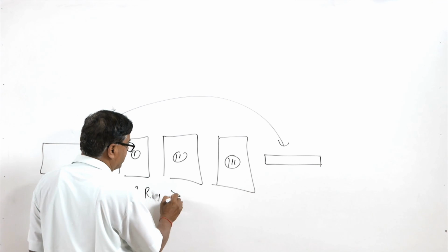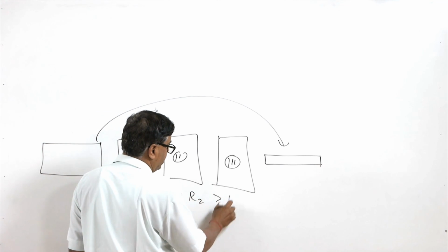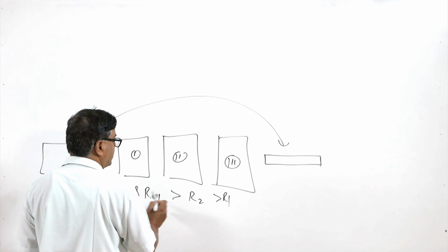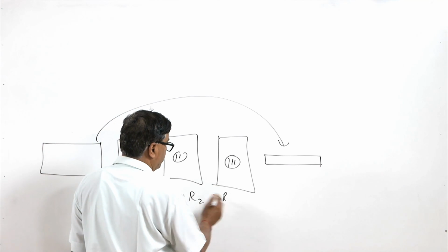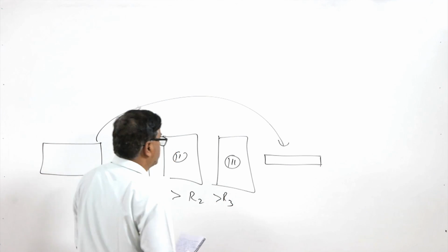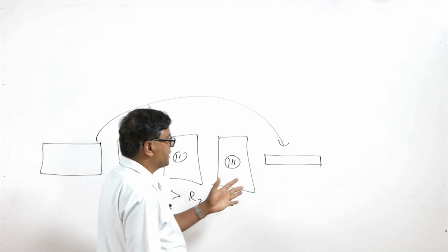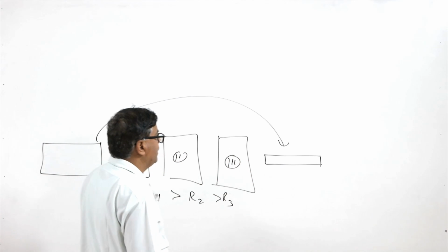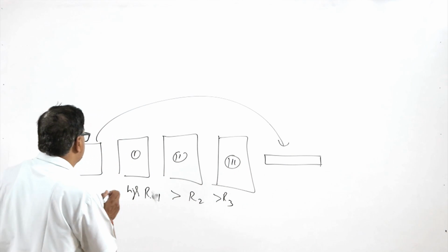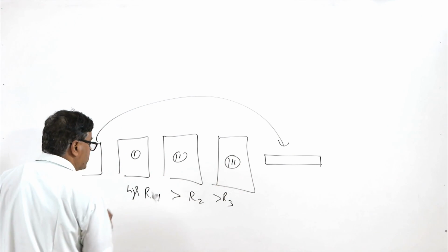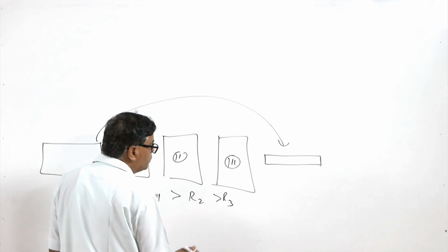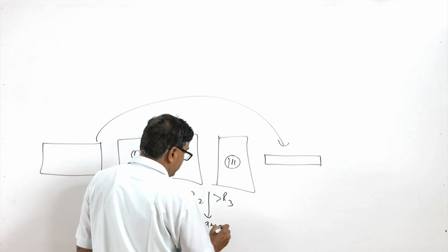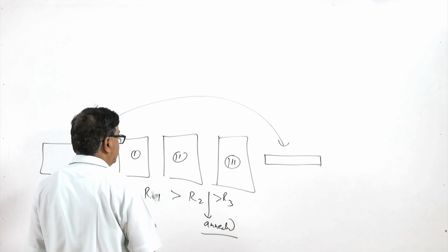So R1 will be greater than R2, and R2 will be greater than R3. Reduction percentages are decreased like this because in this course the metal will be work hardened. Sometimes, if the material is work hardened too much, then in between the stages the material may be annealed in order to restore ductility.